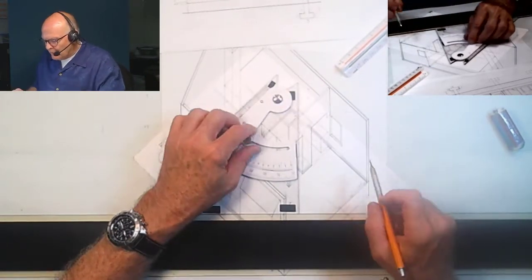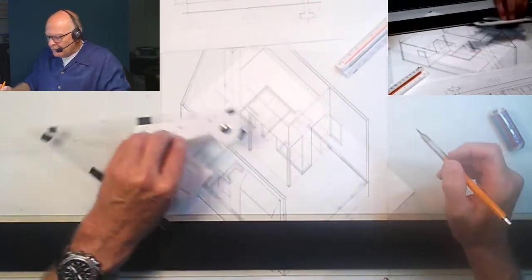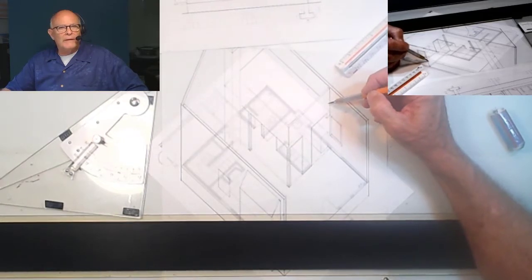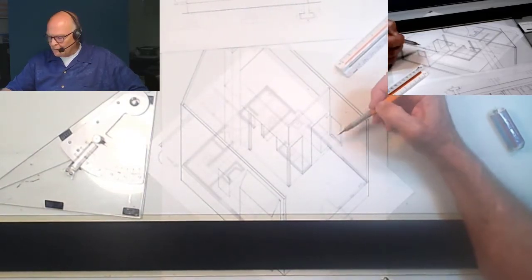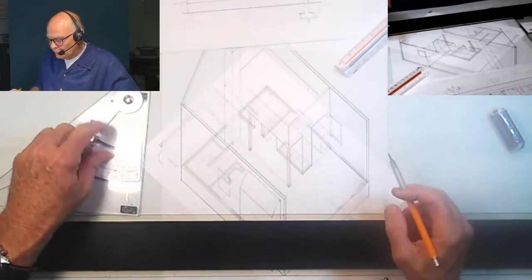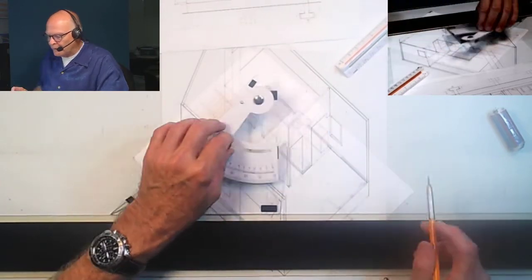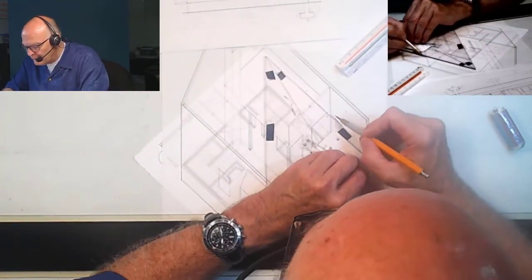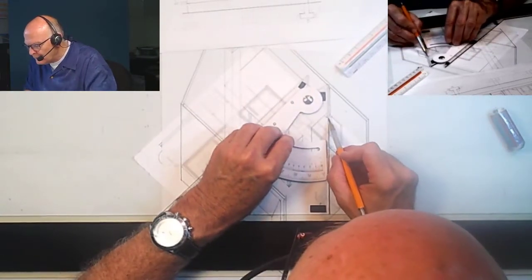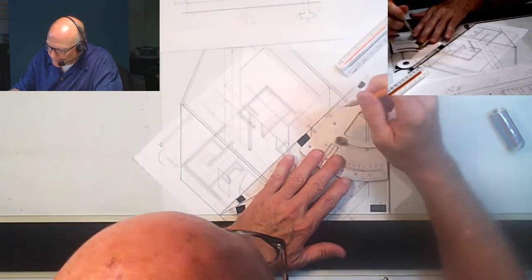Now, the one thing I want you to keep in mind is that the cabinet does not line up with the outer side of that wall. If you look at the plan, there's about a 6-inch break right there, maybe 6 or 7 inch. So be careful when you line up your overhead cabinet, because it's not going to line up in the same way either. So it's going to have a little offset there, and it's going to come out just a bit like that.